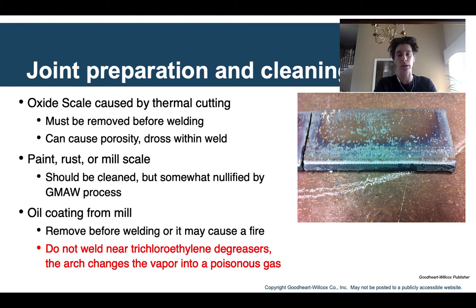It will light on fire. It can create problems, so with fire, you want to be careful. You can use degreasers to clean that oil off, but you do want to make sure that the degreasers are all cleaned up and dried off before you weld there. That vapor can be a poisonous gas. So just be aware of what you are welding on. If you do weld on paint, that's also very hazardous and toxic to your health. So that's another reason why you should clean paint off.